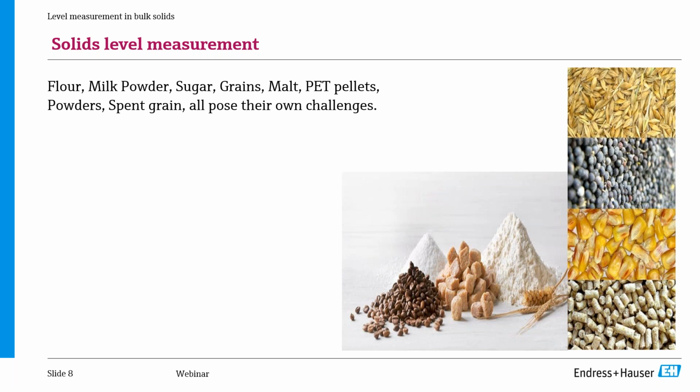The second aspect we need to take into account is the kind of product we're monitoring. There's a huge variability of material types, and each one of them has very unique characteristics. That's a very big challenge when we're talking about the performance of the sensor, especially in the measurement of solids in general. In liquid applications, things are a little bit easier, because you often know you have a very flat surface regardless of the medium properties.